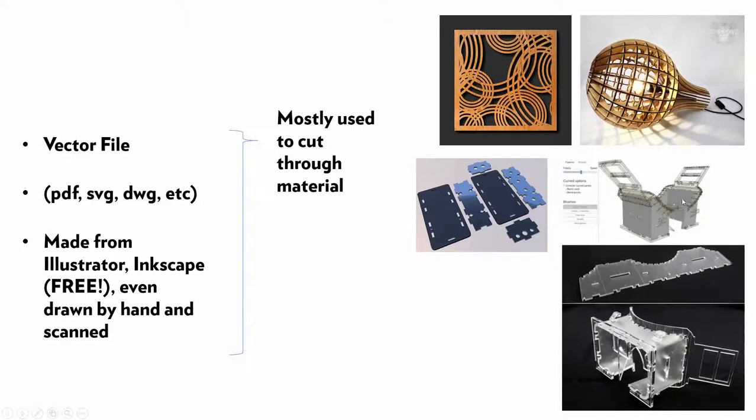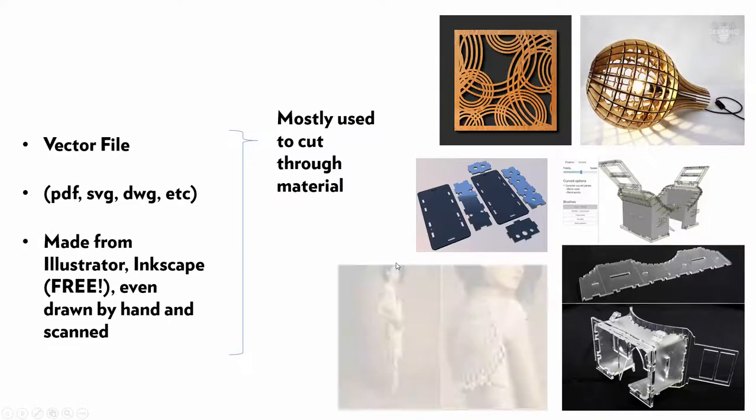And then you can even cut acrylic and score it. You don't have to cut all the way through the material. You can just essentially cut it a little bit so that you can then bend it. And here someone took essentially a kind of Google Cardboard design that allows you to snap your phone in place and make a virtual reality headset display with a laser cut piece of acrylic that is both cut through and also scored for bending. There are even origami type software programs that can help you do that.